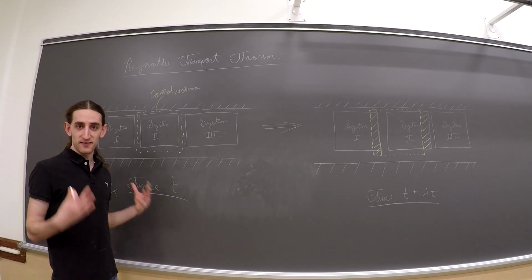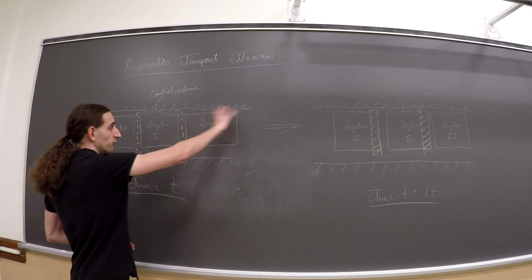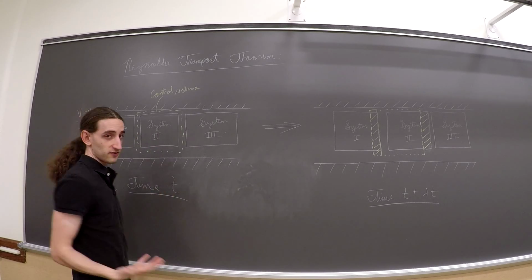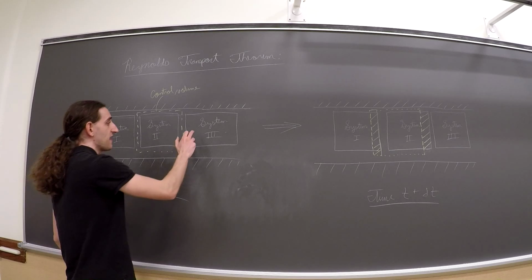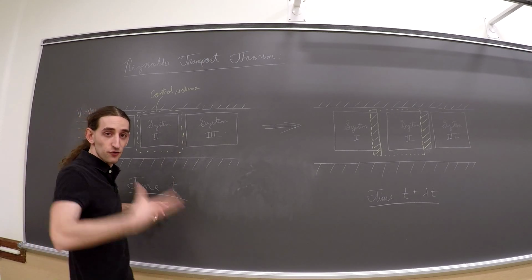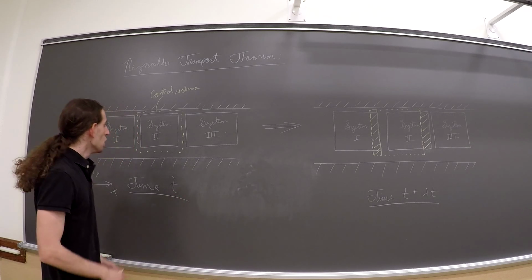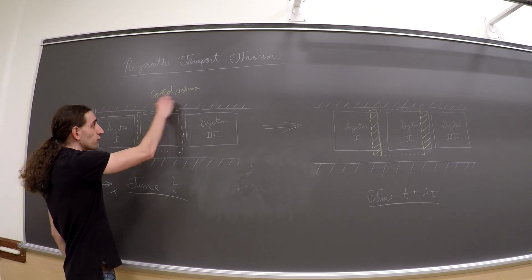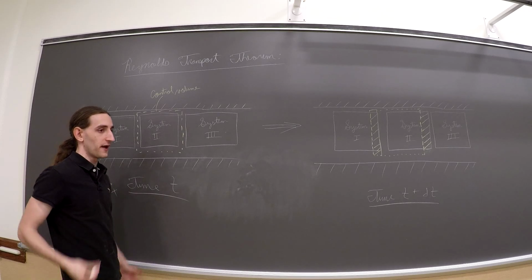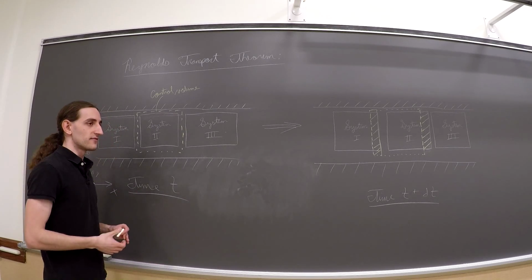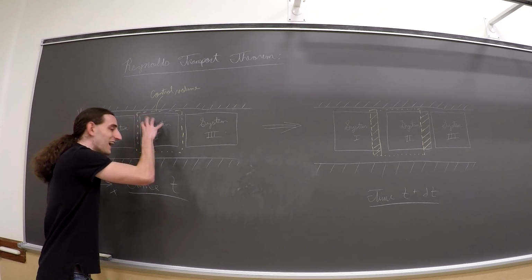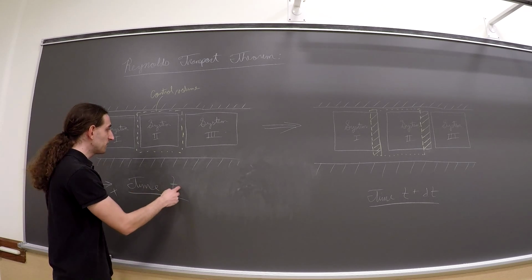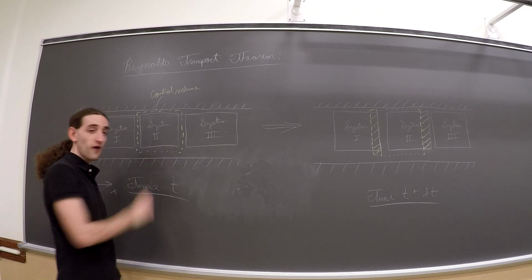Furthermore, we're going to separate the system. We're going to assume right now we have a ton of fluid in here, and we're going to separate that fluid into three separate systems. I'm going to call them system 1, 2, and 3. At time t, the initial time when we start analyzing the problem, system 2 corresponds with the volume we want to analyze, the control volume, which is depicted in yellow here. Just to reiterate, a control volume is a region that we specify that remains constant in volume that we want to analyze. So initially, at time t, system 2 coincides with our control volume.